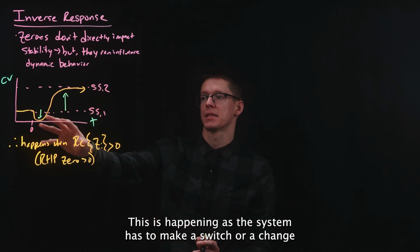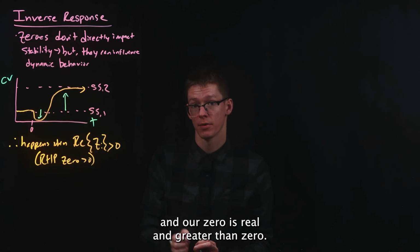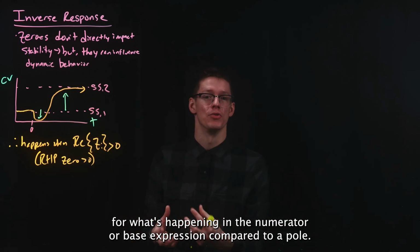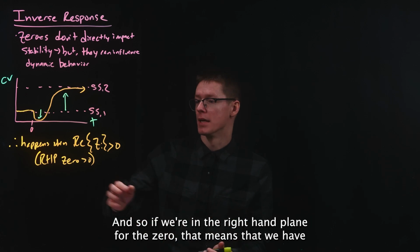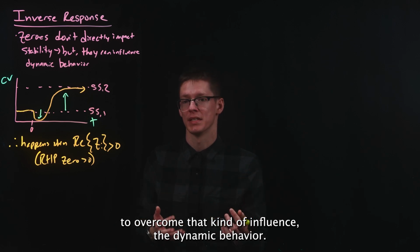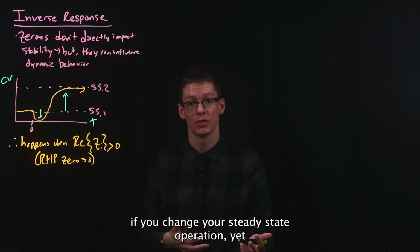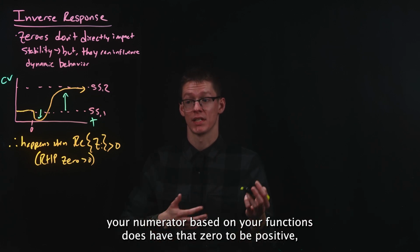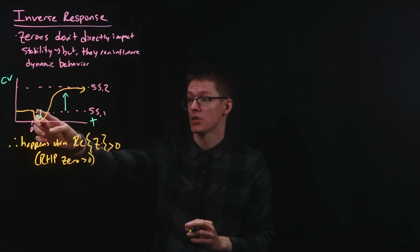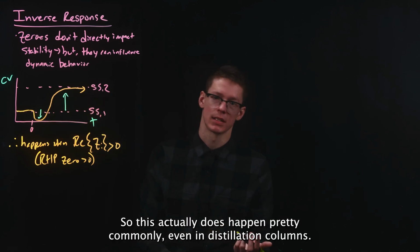This is happening as the system has to make a switch or a change, and our zero is real and greater than 0, with zero being the operative term for what's happening in the numerator-based expression compared to a pole. And so if we're in the right-hand plane for the zero, that means that we have to overcome that kind of influence, the dynamic behavior. You can think of this in a lot of different examples. If you change your steady state operation, yet your numerator-based transfer function does have that zero be positive, then unfortunately you do have to consider there's going to be a quick change that will eventually lead you back into your normalized stability. So this actually does happen pretty commonly, even in distillation columns.